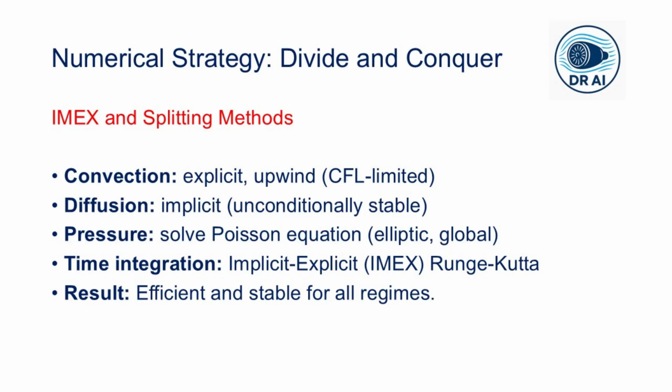Now, moving on, the numerical strategy is that in modern CFD we tackle this with a divide and conquer approach. For convection, the upwind schemes, Riemann solvers, and flux splitting respect the characteristic directions, while for the diffusion viscous terms, we use the central differencing, parabolic terms are straightforward.